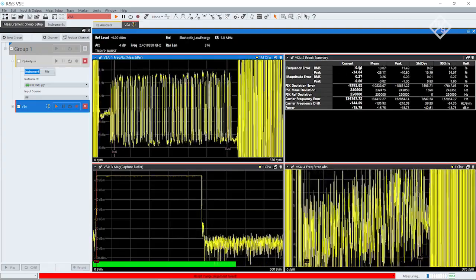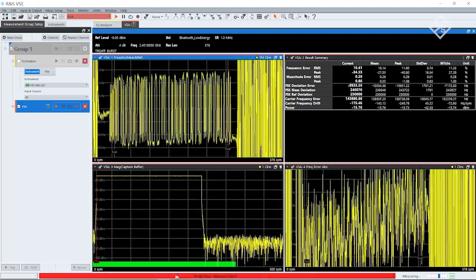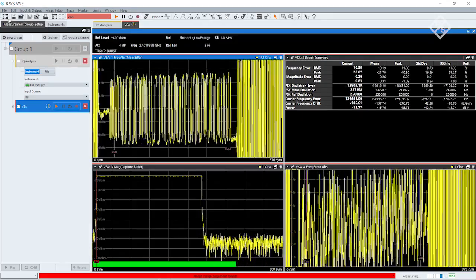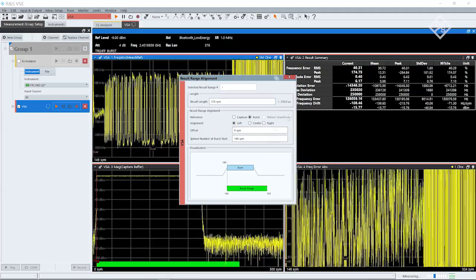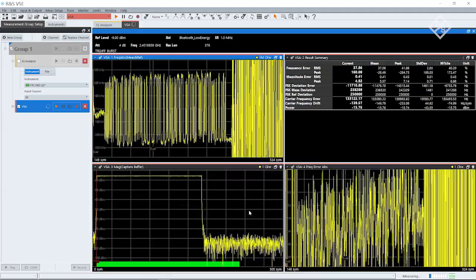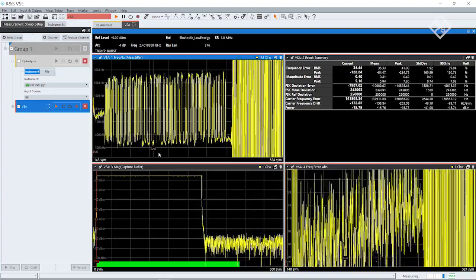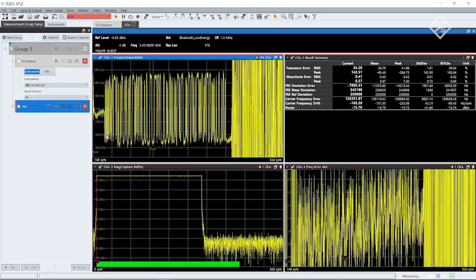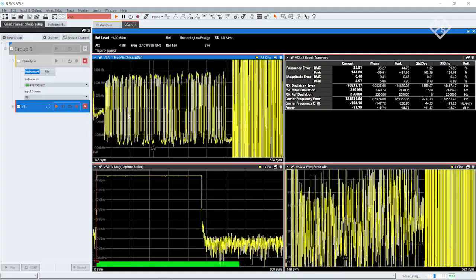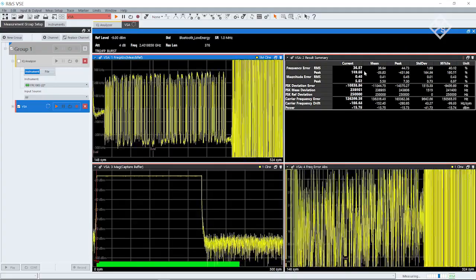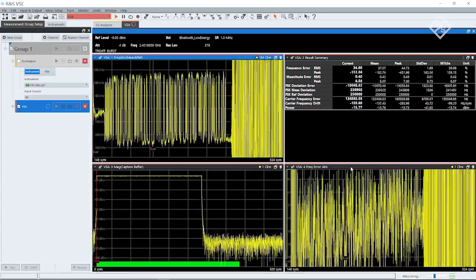And you can get an idea of that here in the frequency error window. And finally, to get rid of this red bar down below, I come into my cut result ranges and put it to the left-hand side to align it. And now we can see that we're actually demodulating a Bluetooth low energy signal. The FSK modulation that's used is going plus and minus 250 kilohertz frequency deviation. And we can see here frequency error in this table, and also a frequency error down here.